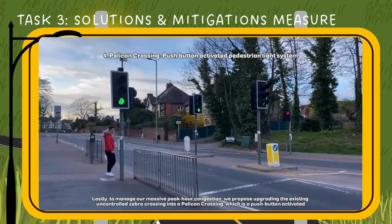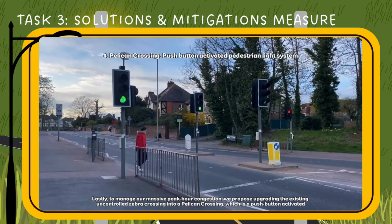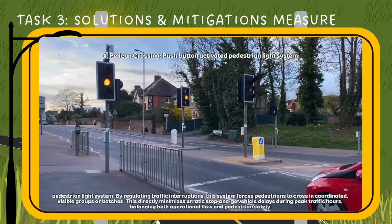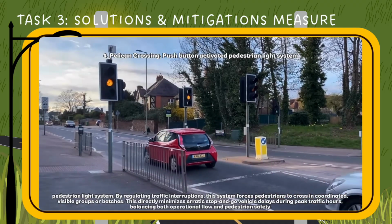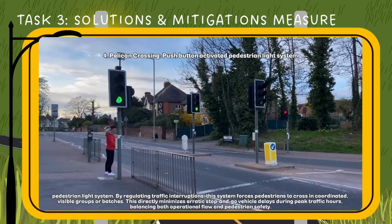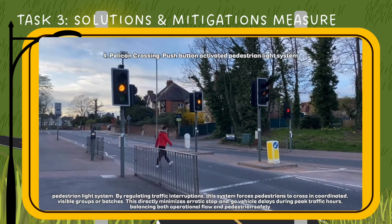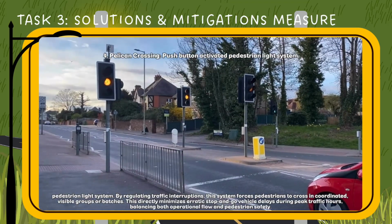Lastly, to manage our massive peak hour congestion, we propose upgrading the existing uncontrolled zebra crossing into a pelican crossing, which is a push-button activated pedestrian light system. By regulating traffic interruptions, this system forces pedestrians to cross in coordinated, visible groups or batches. This directly minimizes erratic stop-and-go vehicle delay during peak traffic hours, balancing both operational flow and pedestrian safety.